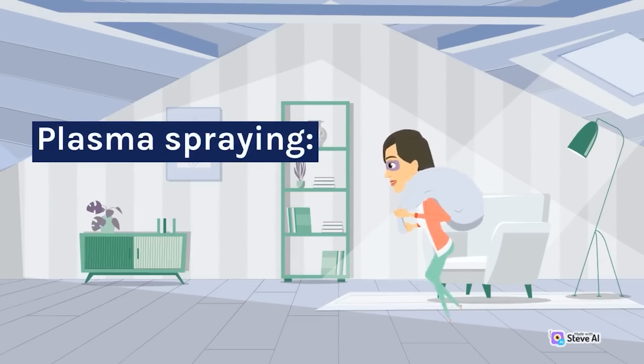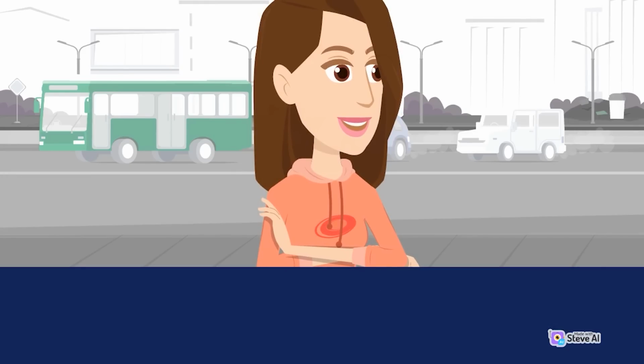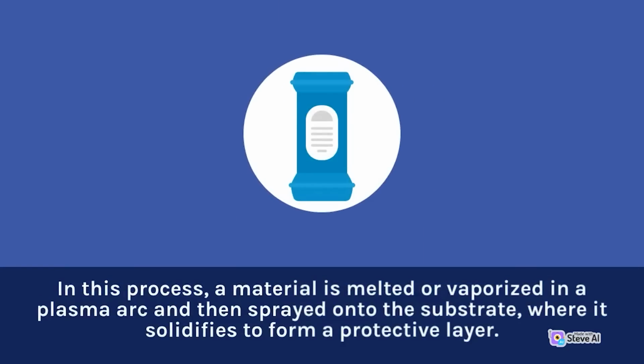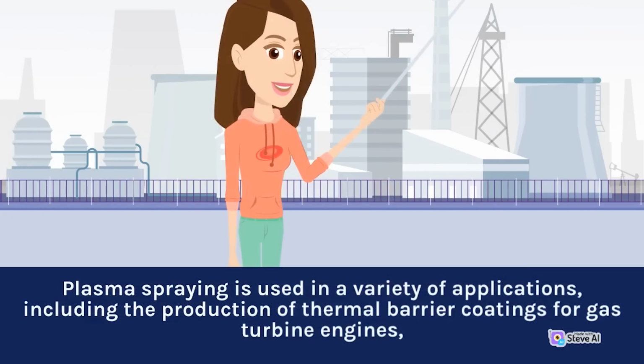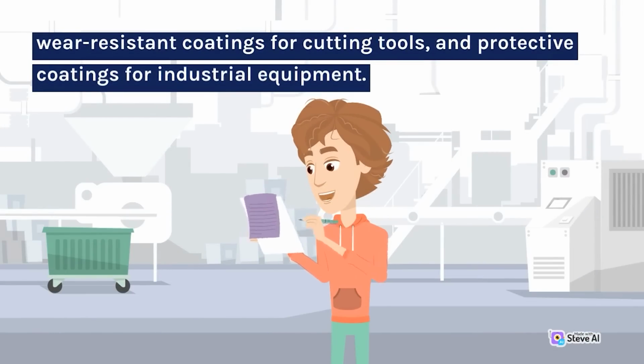Plasma spraying. Plasma spraying is a method used to create a protective layer on a substrate using a high-temperature plasma arc. In this process, a material is melted or vaporized in a plasma arc and then sprayed onto the substrate, where it solidifies to form a protective layer. Plasma spraying is used in a variety of applications, including the production of thermal barrier coatings for gas turbine engines, wear-resistant coatings for cutting tools, and protective coatings for industrial equipment.